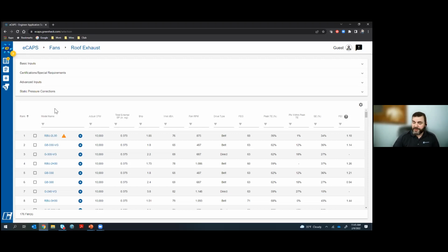And then the second part of the question was, how does FEI compare to fan efficiency? Now, fan efficiency can be looked at in a couple of different ways. We could be looking at total efficiency or static efficiency. And these, the total and static efficiencies, kind of roll into the previous program of FEG, or fan efficiency grade, excuse me, fan efficiency grade took those values. And they're excellent when you look at a fan that's performing at 100% full load. They're very telltale on those values.